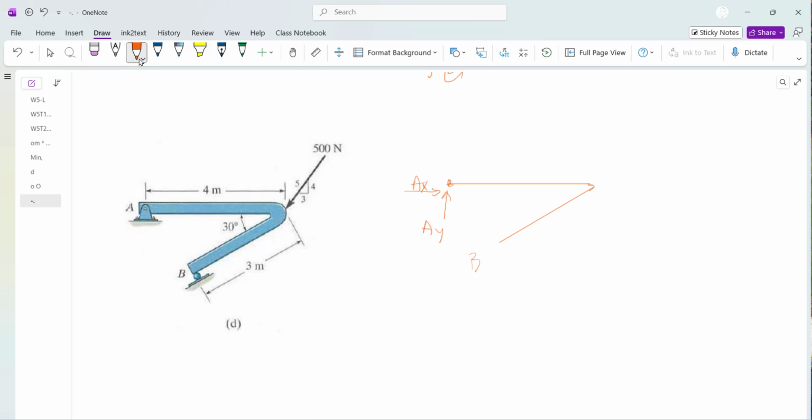Okay. Point B, that's a contact. So if you try to push this normal to the surface of contact, it would resist. So the direction of reaction is only normal. But if you try to push this tangent to this interface, it won't make any resistance. So there is no second component tangent, but there is one normal to the interface. And that is the rule for contact. So this is a contact support, this is a pin support.